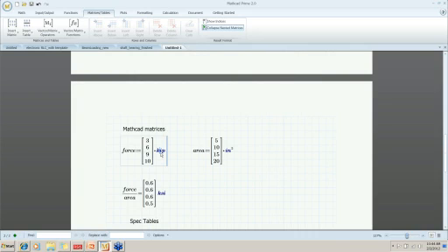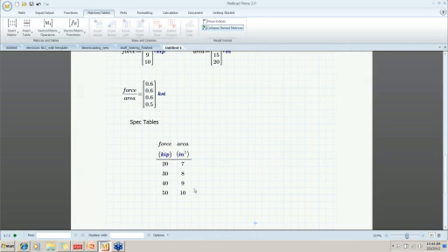So now if we type force equals to display the force variable, you'll see that it contains this column data in units of force. Newtons is the default for SI. Remember, I'm in SI, but we could convert that to kips, and then we'll see the replica of the way we entered in the data. Now let's do the same thing for area.